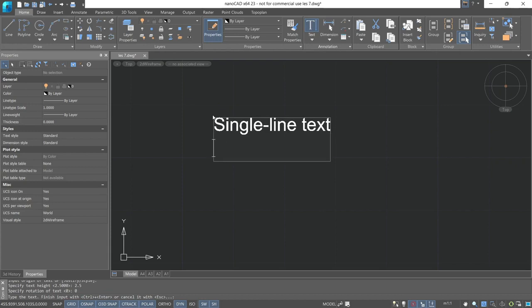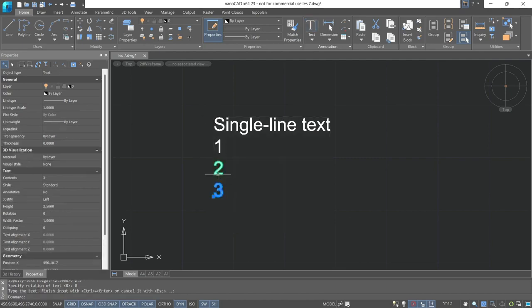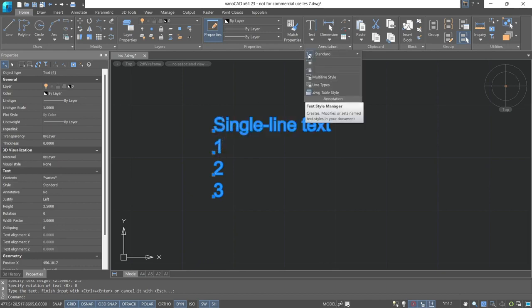If you want to continue creating lines, you can press Enter once. End the command. In this way, after selecting, you can immediately see that they are separate objects, and the current text style chosen for them is the standard, which is located in the text style settings. If necessary, we'll later see that text styles can be changed right in the command line after launching the command.